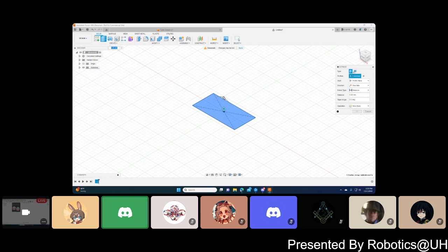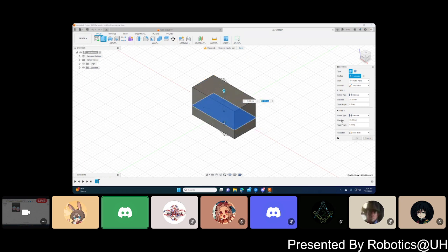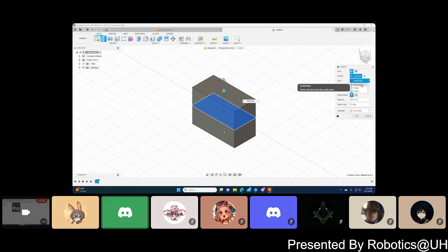Over here, there are different settings. This start just determines where it is starting from. Direction means you can choose if it's on one side like it is. Two sides means you could have two individual extrudes in two different directions. And symmetric means that you're doing two extrudes, but they are the same dimensions, a reflection per se.